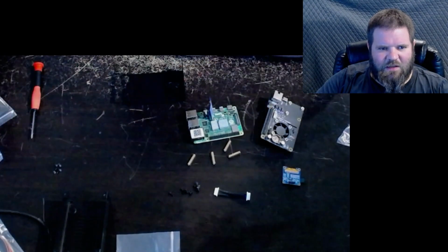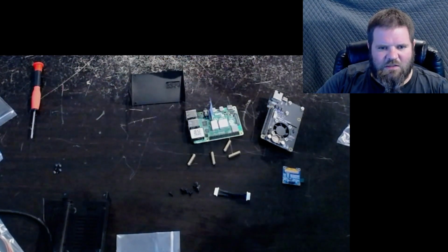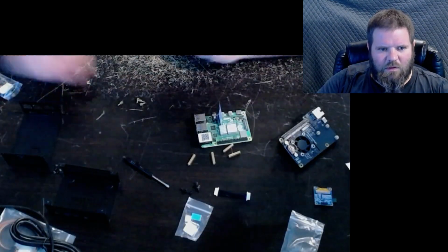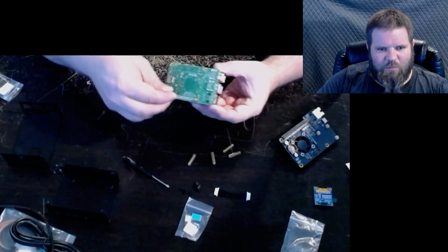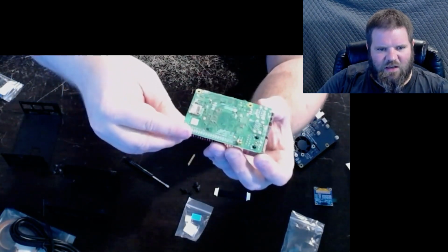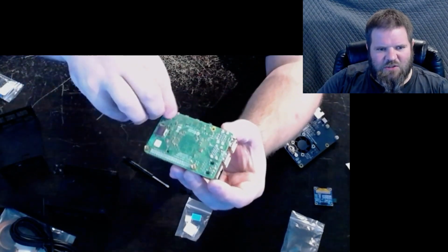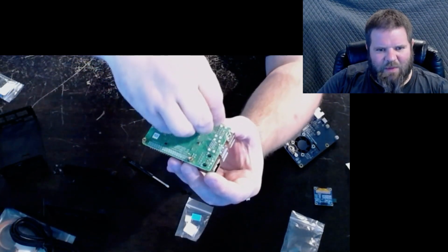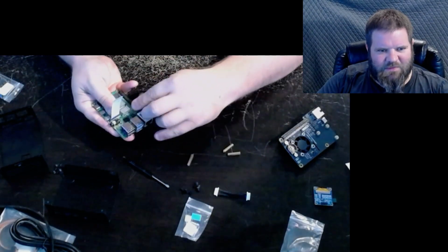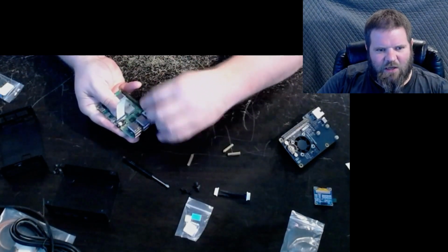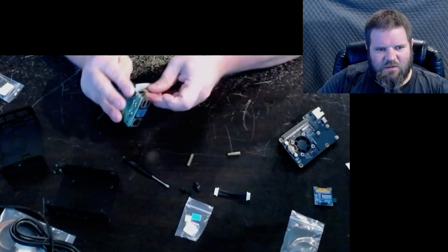So now we're going to take the little short standoffs and get them installed on the bottom of the board. I got the 4 short standoffs. You're going to just put them in the mounting holes of the Raspberry Pi. I set them in there, held them in with my hand, and flipped the board upside down. Just held them in and flipped it upside down. And then you screw the tall standoffs into the threads of the short standoffs.